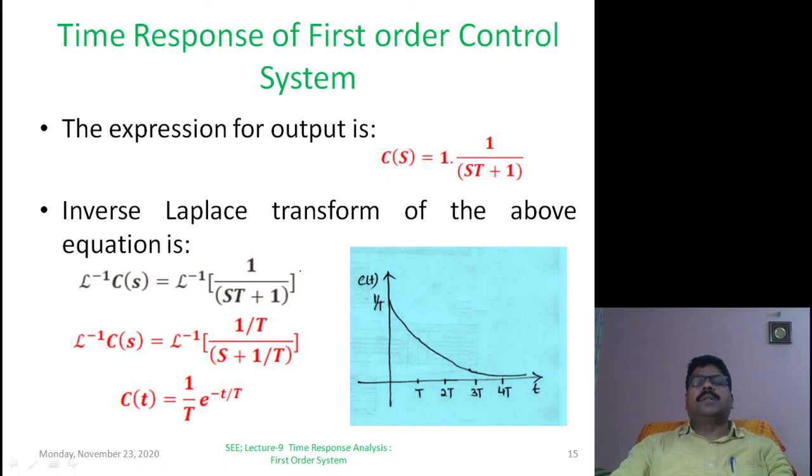If the time constant is lower, the time lag and positional error will be lower. So it is important to see the effect of the time constant. What is the time constant? It is the time taken by the system to reach 63% of the desired output, while the settling time is 4 times the time constant.